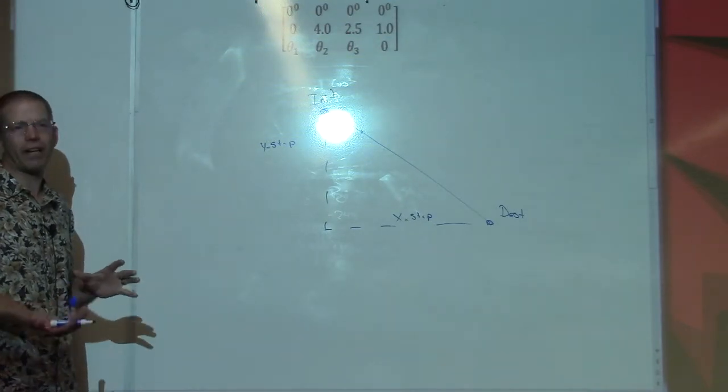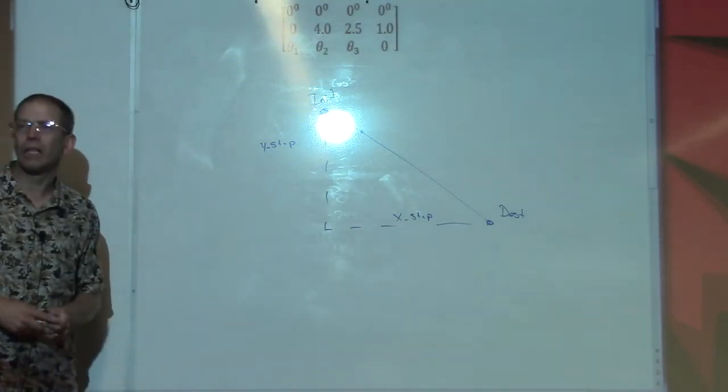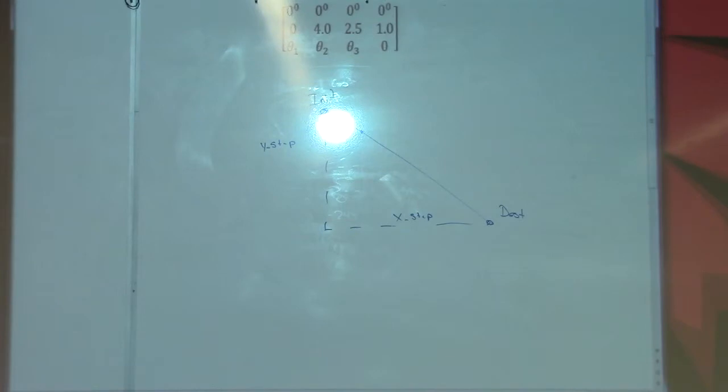and we got it done. In fact, it's going to look very similar to the for loop that we used last week in order to move our joints. Except in this case, we're not going to be iterating through our joint steps, we're going to be iterating through our end effector destinations, okay? So with this then, let's go ahead and take a look at how we can implement this in MATLAB.